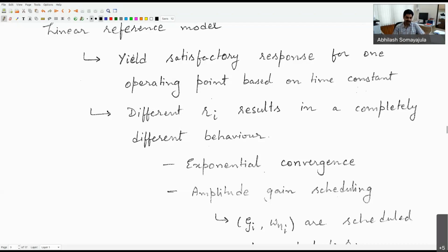But in a real scenario, when we are looking at a practical scenario, there will be certain limits to how much those accelerations can be, how much those velocities can be. I can't have infinite velocities or accelerations in a real system. So it makes sense that when we are considering these systems, the so-called desired trajectory should not be in such a way where it is asking me to generate a velocity which is greater than what is possible.